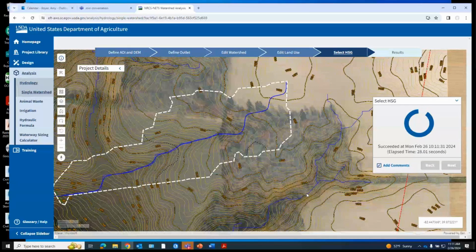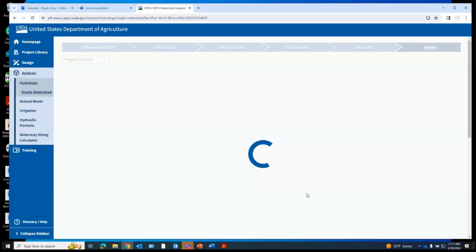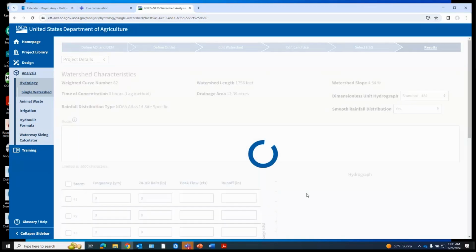We have a question in the chat about what makes woods crops good versus fair versus poor. So this goes back to our hydrology TDP. We're going to consider that as far as the crops by land use cover. Do we have any cover on it? Is it bare ground? Do we have a little bit of cover? Do we have a lot of corn stalk residue on there?